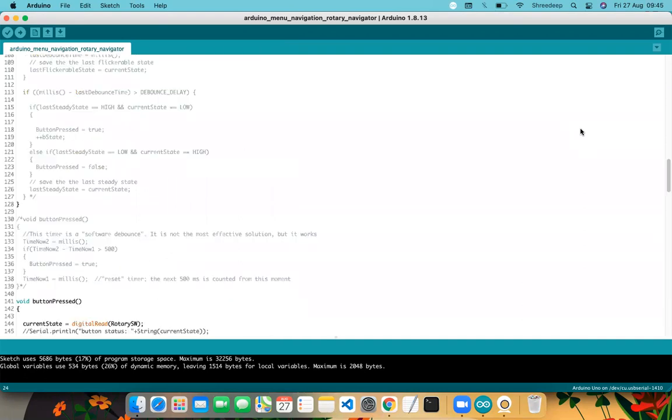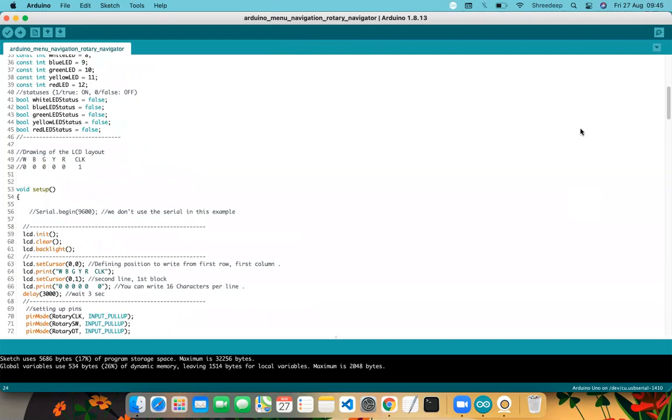But this needs a proper understanding of which inputs of the rotary encoder need to be initialized with interrupt assignments, and which are the normal inputs. And firstly, see that my LCD display is not flickering, right? That's the most important thing.